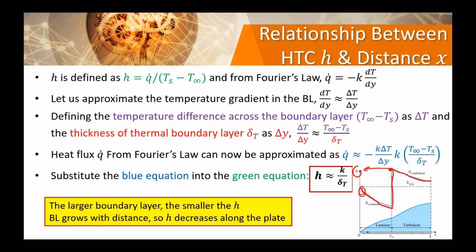But in turbulent flow, the fluid is not behaving nicely like layers of paper. It moves up and down, forward and backward. And due to this vertical mixing, this vertical motion of the fluid, heat gets transferred more efficiently, rather than just calm and steady movement. The heat moves very chaotically because of the up and down, forward and backward motion of the fluid.